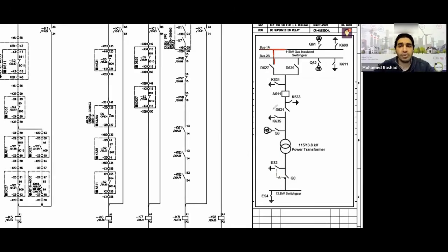Consider that you didn't have all these interlocks and it was possible to operate the disconnector. Now, if this part below is all closed and there are loads present, there's still no electricity. Let's assume this side has 115 kilovolts and is live, and this other side is essentially a load, so the voltage here is 0. Great. If you close this disconnector, will an arc be generated at the terminals or not?